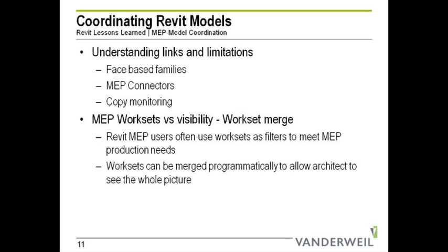Another thing that is often overlooked is MEP work sets are used very differently than architectural work sets. A work set is designed to be able to split up the work. I can, say, assign the first level of a building to a work set, and then I can check it out so that only I can work on it right now, and no one else can modify that until I check it back in, and then they can check it out, etc.